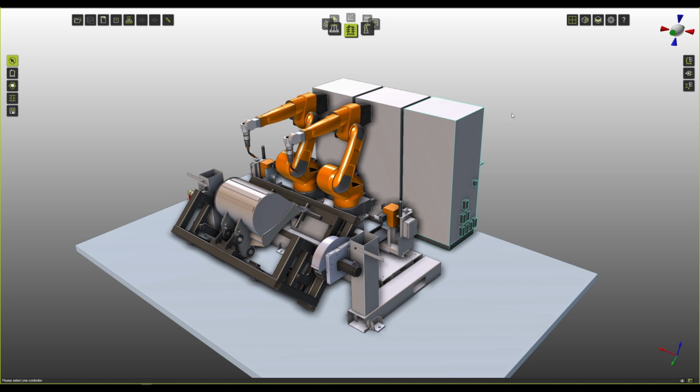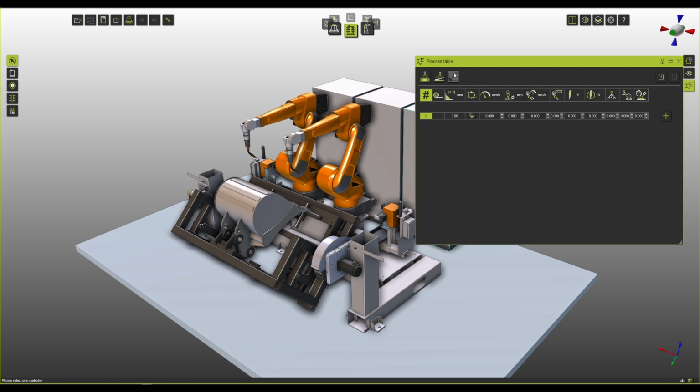First, we're going to begin with our controller section. Here in our controller, we have a section called a process table. This process table is designed to gather the same amount of information that you get out of our welding testing. Many times you will gather this with experience from the welding process. And here you can see, if I'm making a certain welding type with a certain size and a certain position, then I'm going to need this speed, this wire diameter, voltage, current, and all of the different settings that are necessary to create this particular weld that I want to achieve.